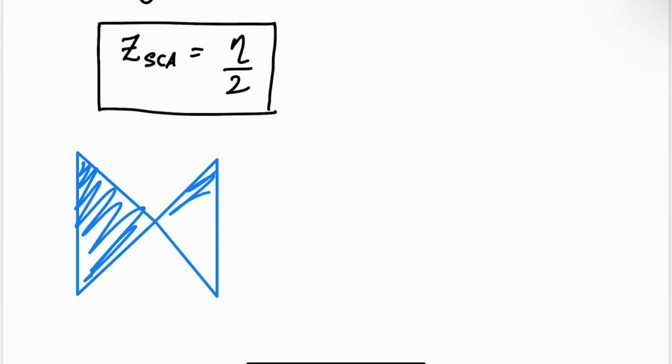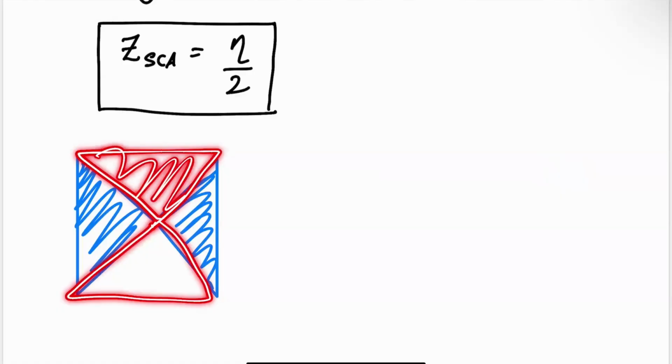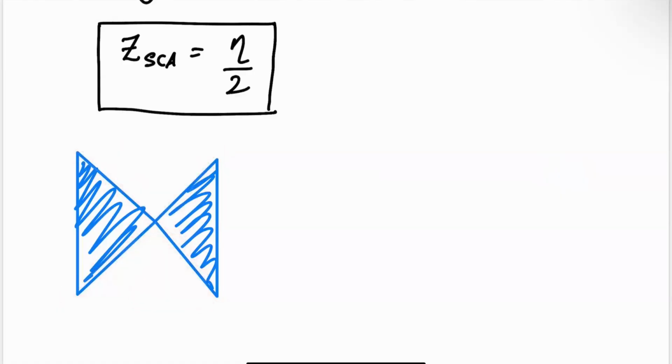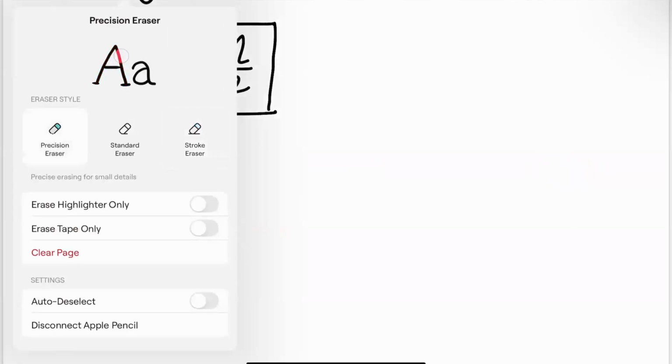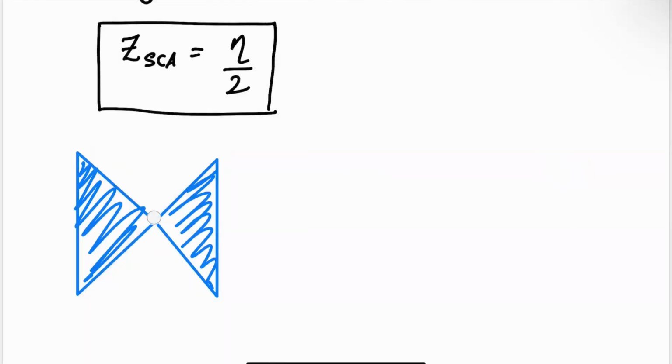This is PEC. So the complementary part of it would have an antenna like that. And of course, it's not the same orientation, but from the point of view of the port, which is down here, it looks like the same antenna. So that's why bow tie dipoles have very high bandwidth. I can make a small gap here in order to excite it, like this. Then I place my excitation across this.